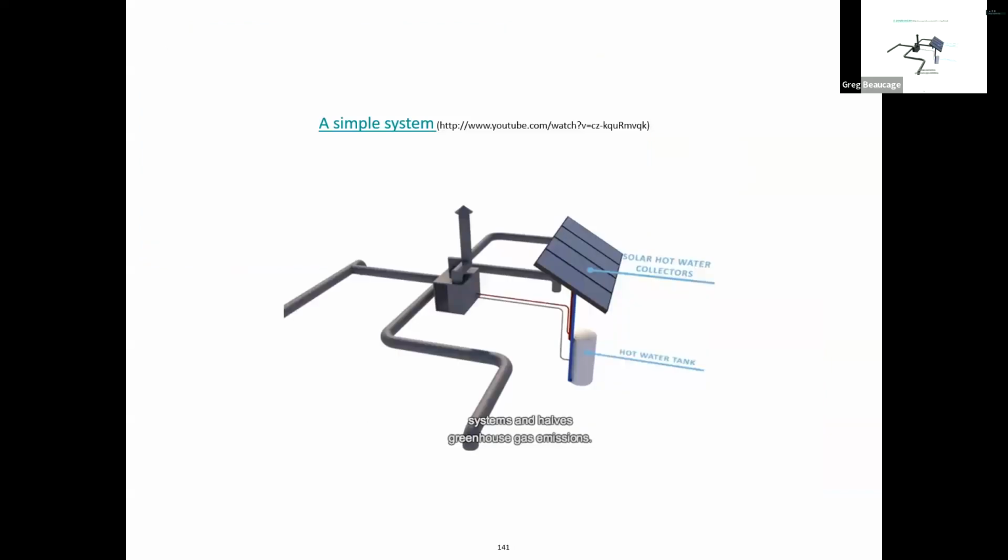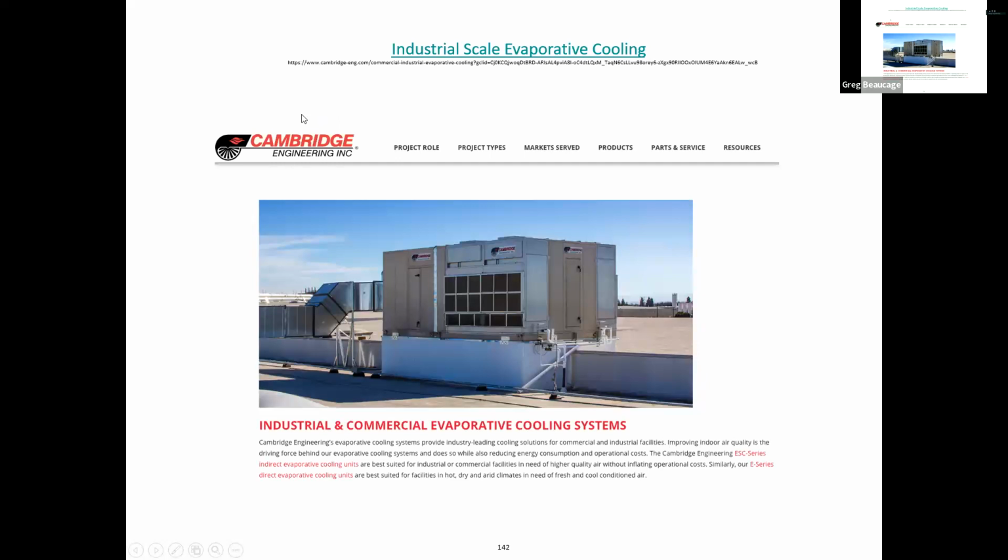So that kind of machine has been made. People make that and it uses solar heat to dehumidify the air and then puts it through a humidification process to cool it down. So you end up with perfect air coming out of it. It's possible to do it using just the solar heat collectors, then some kind of engineered system to go through the psychrometric chart in the right direction.